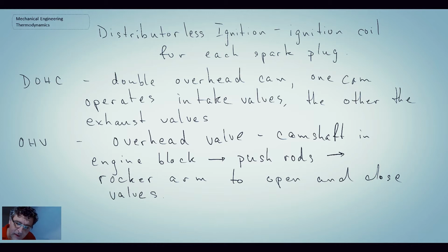So to draw a little schematic of this, down here would be your crankshaft. Your camshaft might be connected to that mechanically with either a timing chain or some other mechanical connection. And then there's a lobe on the camshaft, and then that pushes this push rod up and down. And then here you would have your rocker arm. So I'll just draw it like that.